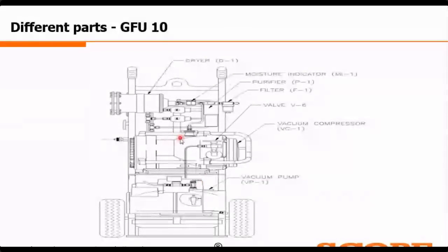Along with that, we are also having one main compressor, that is nothing but the reciprocating compressor, which is creating the high pressure. The application of the reciprocating compressor, we all know, is that it will generate the pressure to transfer the gas at very high pressure. So that is the work of the reciprocating compressor. Additionally, we are having the vacuum compressor also. The application of the vacuum compressor is nothing but the better recovery of SF6. So the vacuum compressor is the compressor you are using here for the better recovery of SF6.